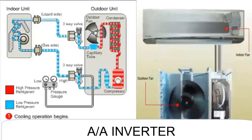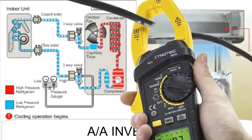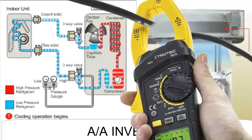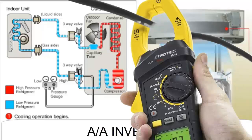3. If the voltage is normal, focus your attention on the unit's electrical consumption. For this, you will need a clamp meter. With the clamp meter set to AC mode, measure the current in one of the power cables of the unit.